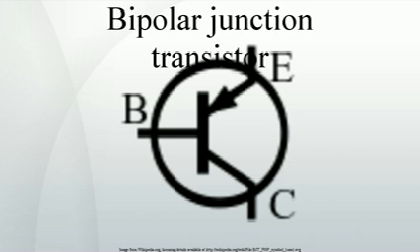Hybrid pi model. The hybrid pi model is a popular circuit model used for analyzing the small signal behavior of bipolar junction and field effect transistors. Sometimes it is also called the Giacoletto model because it was introduced by L. J. Giacoletto in 1969. The model can be quite accurate for low-frequency circuits and can easily be adapted for higher-frequency circuits with the addition of appropriate inter-electrode capacitances and other parasitic elements.